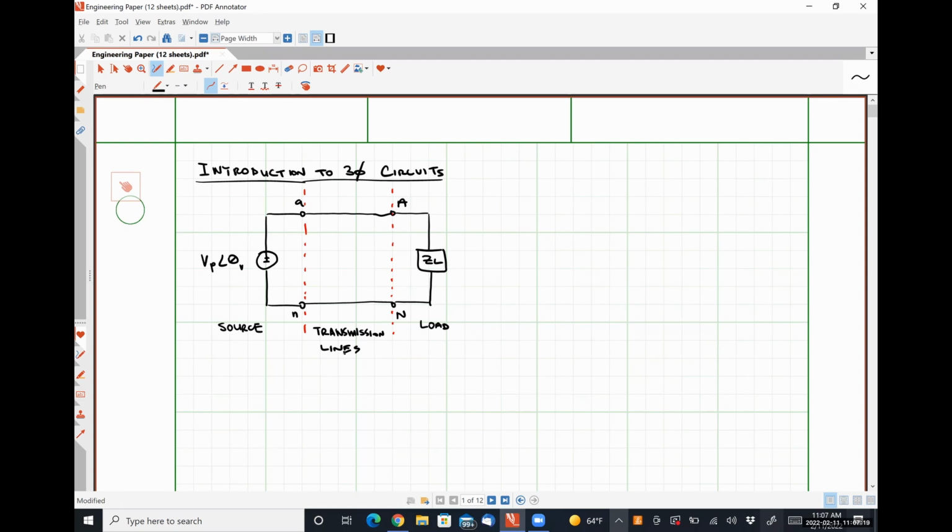So our power distribution lines really wouldn't be considered transmission lines because the frequency of excitation is so slow, right? Power is distributed at 60 hertz, which means the wavelength of that line is something like the distance between here and Alaska. So it doesn't really look different at different points along the wire particularly. But anyway, that's the thing you'll learn about in 401.